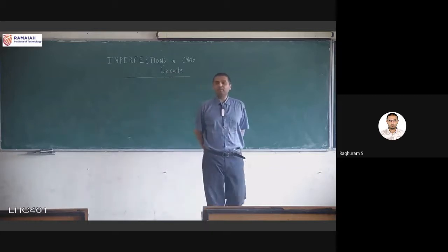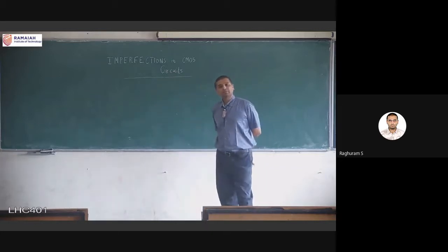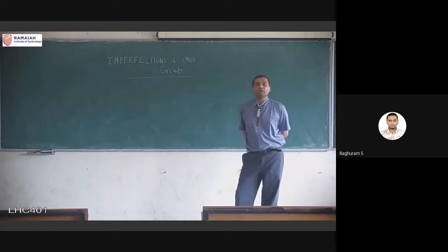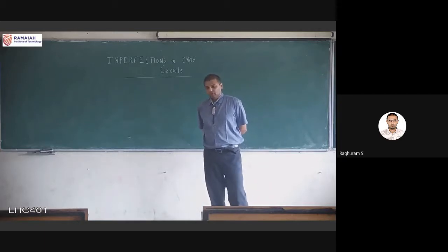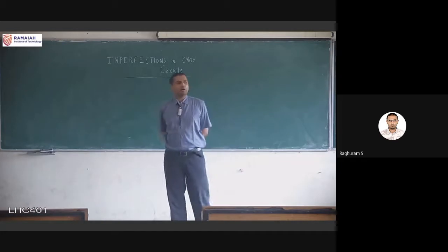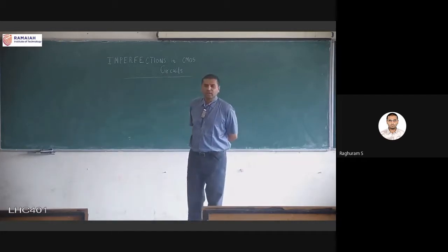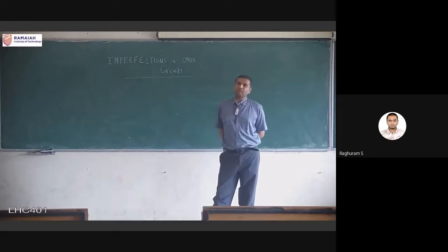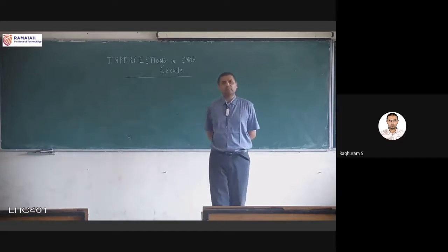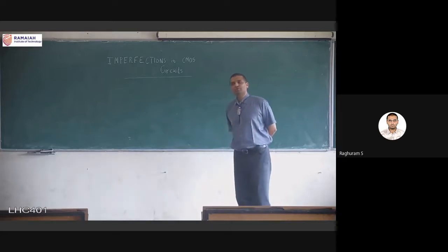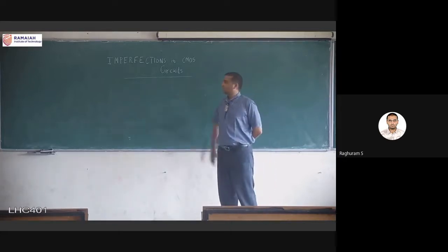You could have PMOS transistors below and PMOS transistors above, which means I can work with a simpler technology. I don't need CMOS technology. I can just use PMOS only technology, which is going to be cheaper, right? That is, if I have PMOS transistors above and below. And likewise, completely replace all the PMOS transistors with NMOS transistors: have only NMOS transistors above and only NMOS transistors below. Again, I don't need CMOS technology; I can have NMOS only technology. Both of these were prevalent, but there are some issues in the operation. That is what we are going to see here.